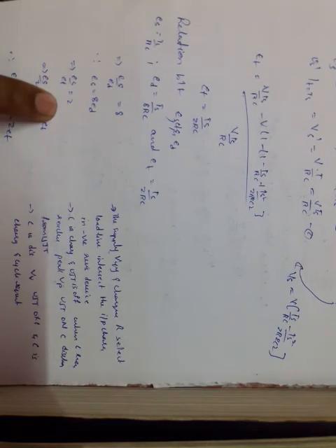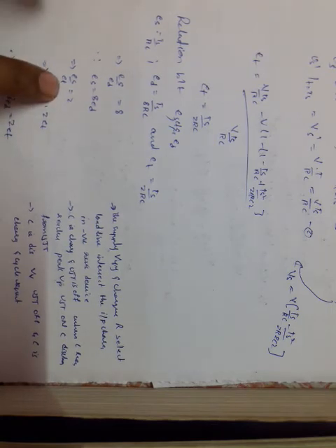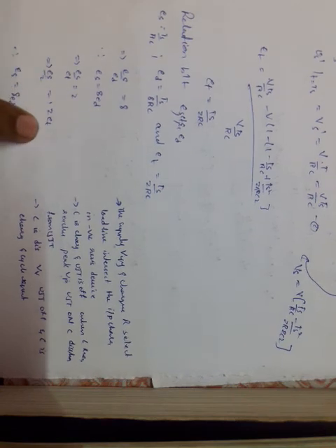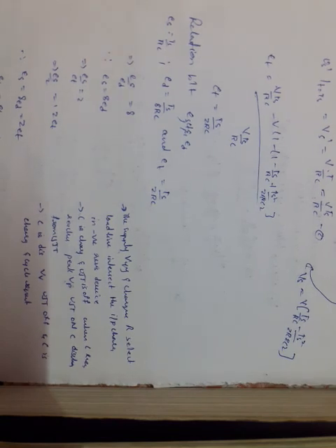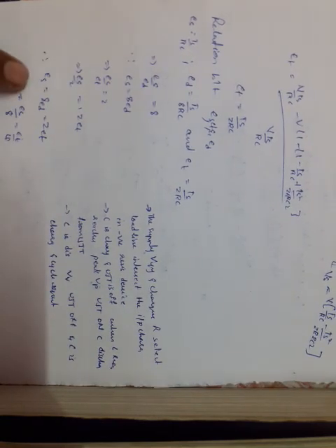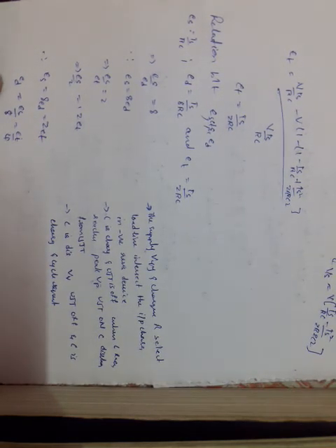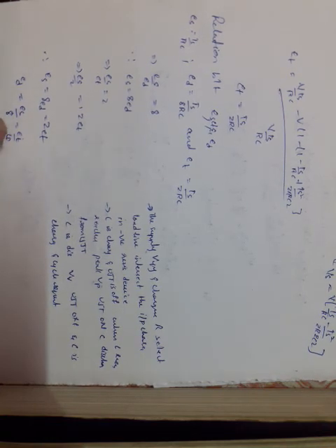Okay, this is completed. Again we substitute the values, so Es is equal to 2 Et. After completing this, the total relationship we get is Es equal to 8 Ed equal to 2 Et. Therefore Ed is equal to Es by 8, equal to Et by 4. This is how you calculate the relationship between the transmission error, slope error and displacement error.